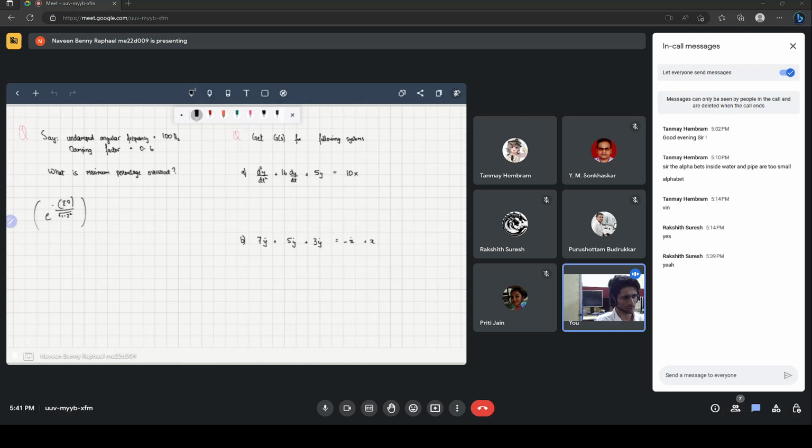We had this discussion a while back, essentially because there are multiple types of rise time, and we usually have to specify what percentage you are trying to reach. For example, there's a 90% rise time, that is the time taken for the output to reach 90% of its final value and things like that. So in the slides, the rise time given is for the 100% rise time.